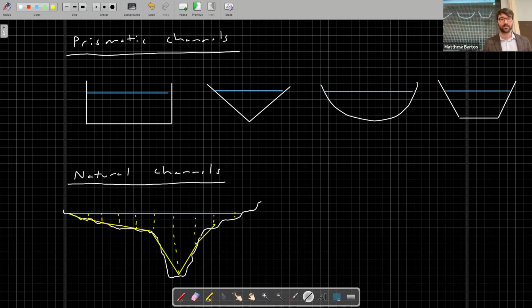And then from this, you compute the hydraulic geometries for each of these segments. And then from that, you can get the overall hydraulic geometry for the entire channel. So this is how it would be done in a computer program like HEC-RAS, which they'll be working with on one of the labs later on in class. Okay, any questions on hydraulic geometry so far?